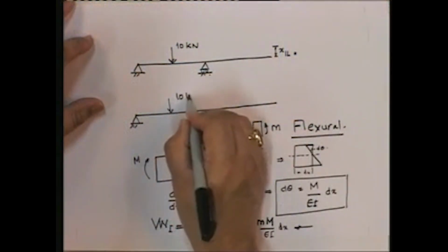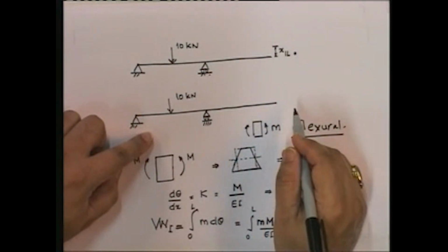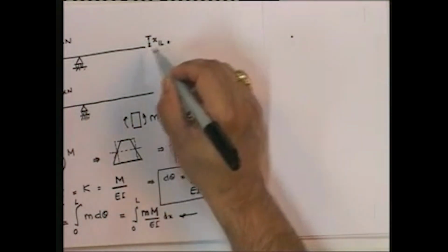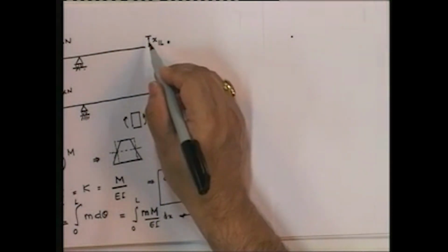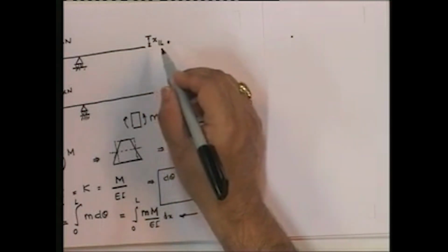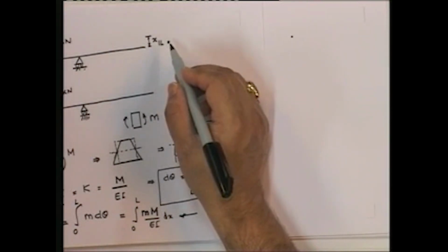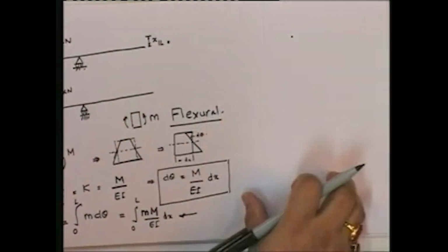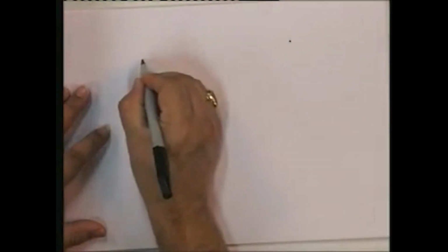Therefore, what we need to do here is find out the displacement in this particular case. To find this displacement, we find the bending moment due to this force. Then, because we are trying to find this displacement, you have to apply a virtual force corresponding to this displacement, find the bending moment due to that, and then go through the virtual force method. So let us do this process.